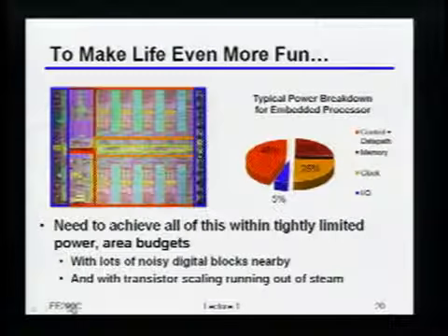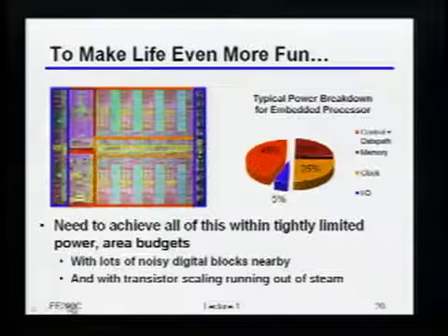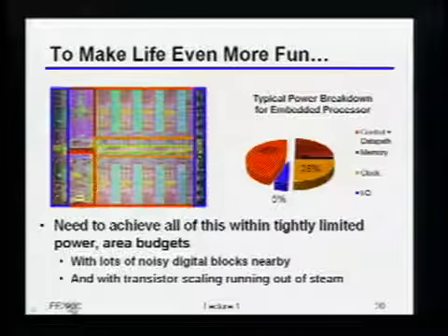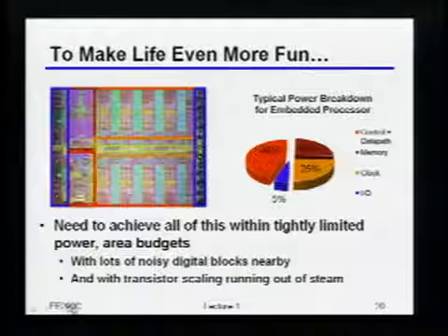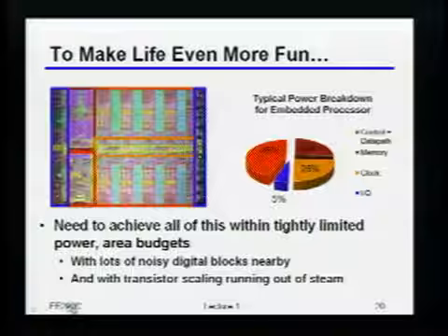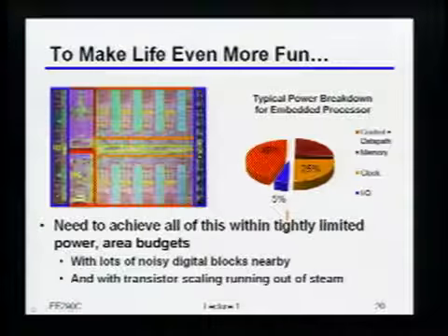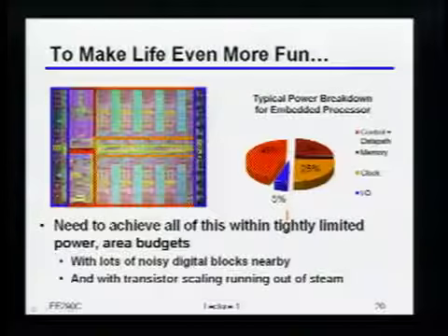So just to make life even a little bit more fun, as Linkai was asking before, what's the typical power breakdown? Well, obviously it depends on the exact application. But just as an example, if I look at the embedded processor that may be sitting in your iPhone, well, you want that processor there because you actually want it to compute something, right? So usually if you look at how much power was budgeted to actually doing the IOs, it's usually only on the order of 5 or 10% or so, okay?